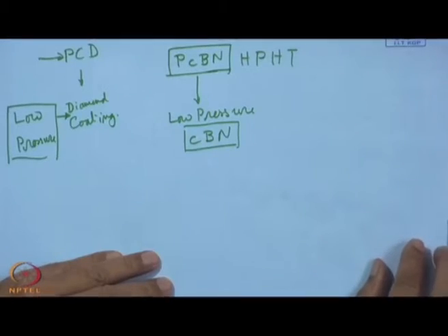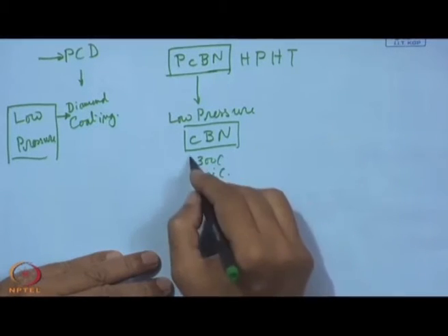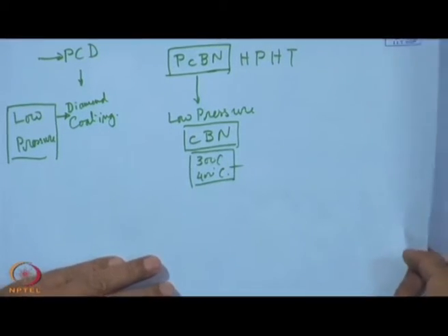With the availability of coating, the user has much more flexibility. He can choose this coating, and it can be applied to various complex geometries of the cutting tool, such as end mill cutters with this CBN coating, which is the result of this low pressure, low temperature synthesis, handled at around 300 to 400 degrees centigrade. That is in essence the speciality of this process.